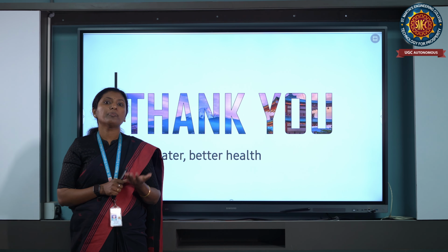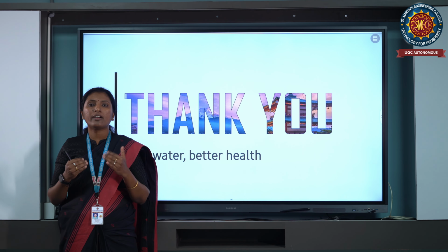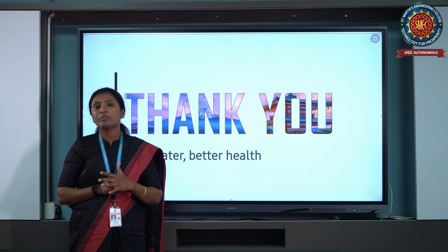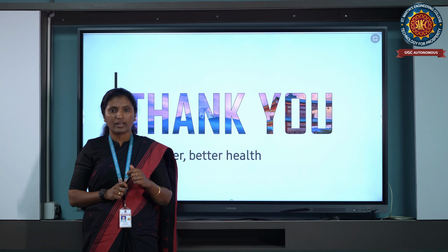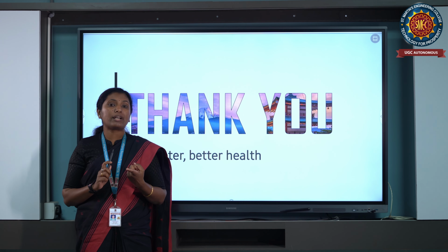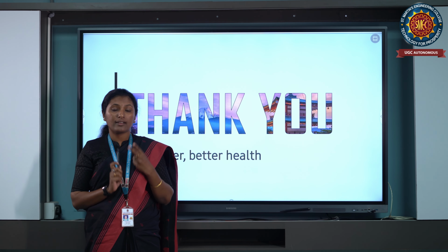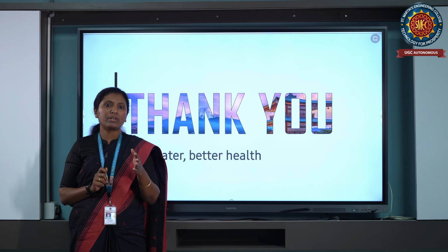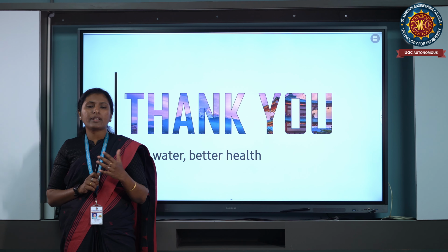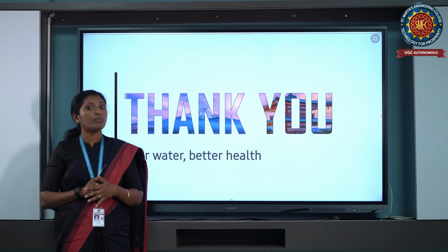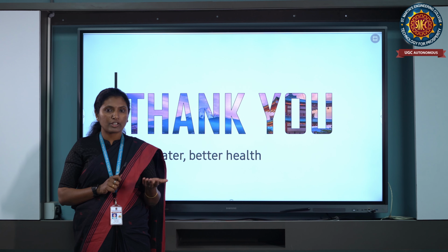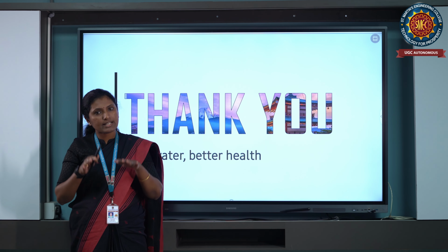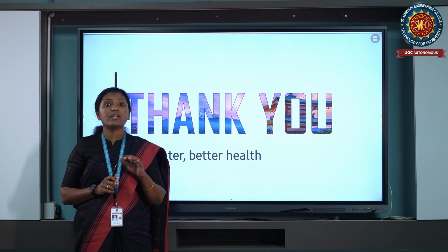Next, the last thing we told: if the water has a high amount of fluorine, how can you remove the fluorine? What is the technique? That is the Nalgonda technique. What do we add in the Nalgonda technique? One is alum, and the next one is calcium oxide or calcium hydroxide. Alum, in the form of aluminum sulfate, is added. That aluminum sulfate will form aluminum hydroxide, which will combine with the fluorine to form aluminum fluoride. Aluminum fluoride is a precipitate, and it will settle down. That step is known as sedimentation.